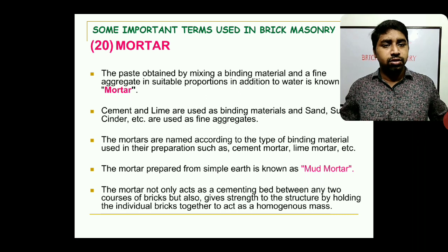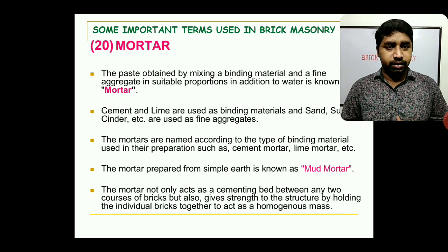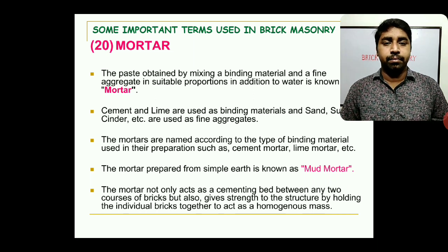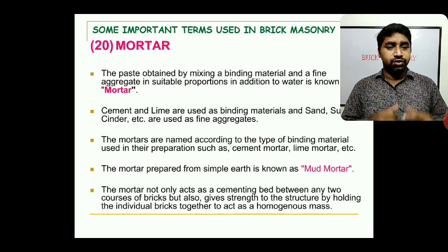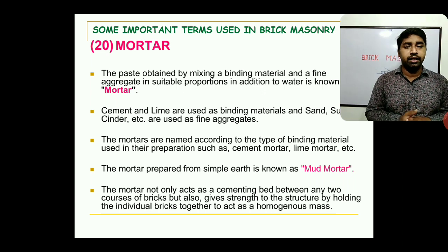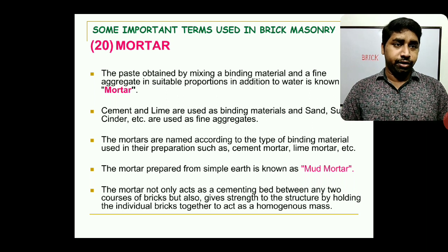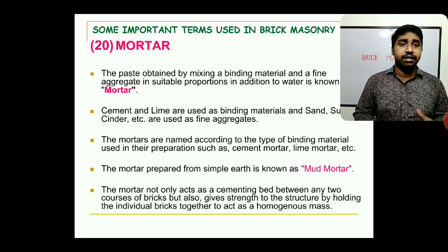So it gives you a bonding between the brickwork, right? The mortar not only acts as a cementing bed between the courses of brick, but also gives strength to the structure by holding the individual bricks as a homogeneous mass. So that is the advantage with this mortar. So these are the basic terms related to brick masonry.